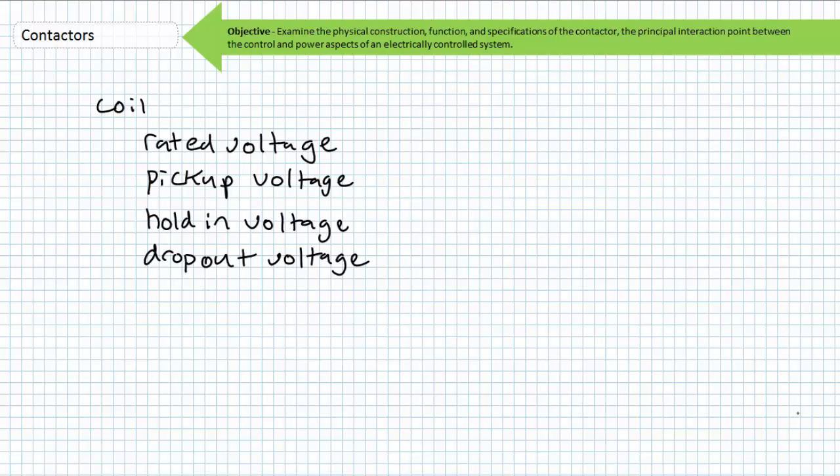Again, coils with both the same AC and DC voltage rating are not interchangeable. Those with an understanding of reactance and impedance realize a coil of wire presents both a resistive and inductive impedance to an AC voltage source, whereas DC voltage sees only the resistive portion. Current draw for the same coil operated at AC versus DC voltages will be astoundingly different. Additionally, an AC coil experiences a slight inrush current upon being energized in comparison to that of its sealed-in or stable value.